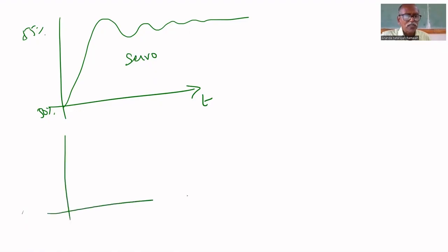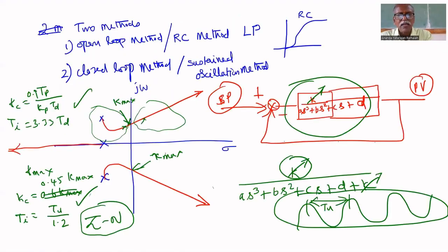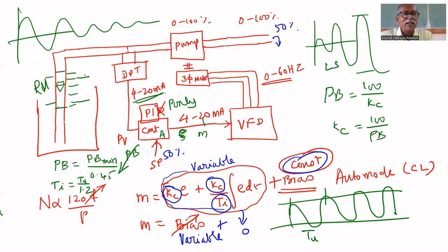For the regulatory response, here one tap, a hand valve, will be there. It is here. Before that rotameter, one valve is there. You slightly close that. Actually, you are introducing some resistance in the tube. That's why flow rate will decrease. Or if you open, resistance will decrease. That's why flow rate will increase. So you are introducing the load here, the disturbance here.